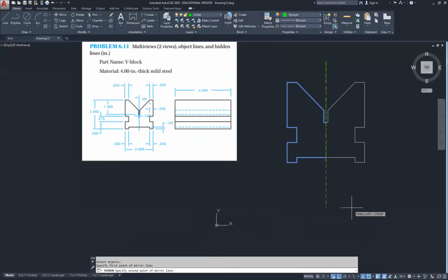Also, if you have any other objects that have snap points, make sure you avoid this. We need this line to be perfectly going from top to bottom or bottom to top. Once I go ahead and select, the prompt at the bottom here will say erase source object. Yes, no. The default is set to no. If yours is set to yes, make sure to put no in. I only have to hit the enter key because mine already says no.